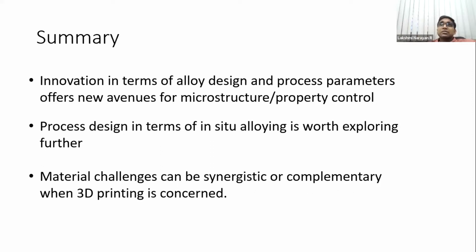Similarly, metallic glasses also, if you want to use a metallic glass implant, you can use niobium powder and you can create some kind of innovation to improve its mechanical properties. So we also saw several variations in process design. We generally assume that we look at a single bead test, but it's not necessary. We need to also look at how the entire build behaves and also how the melt pool dynamic changes when we use a different strategy or a different spot size or a different spot type. Okay, it's either a Gaussian profile or a top hat profile.